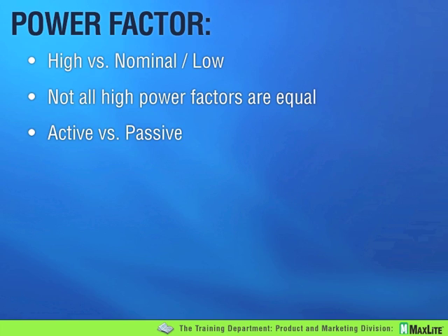These days we have no devices that are low power factor. CFLs might surprise you to know are only a 0.5 or a nominal power factor, which is very interesting because the power companies are the ones who are providing them for the most part and bringing them to market, whereas they are also the ones who have to pay more, watt for watt, for the ratio of active power to apparent power.